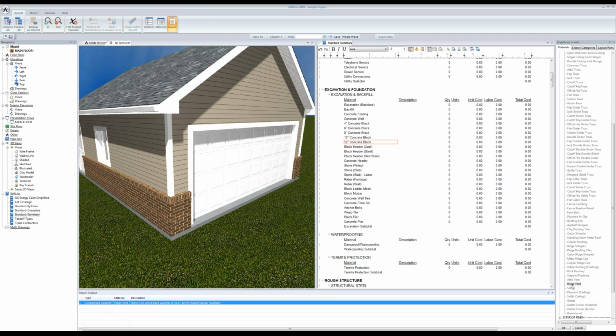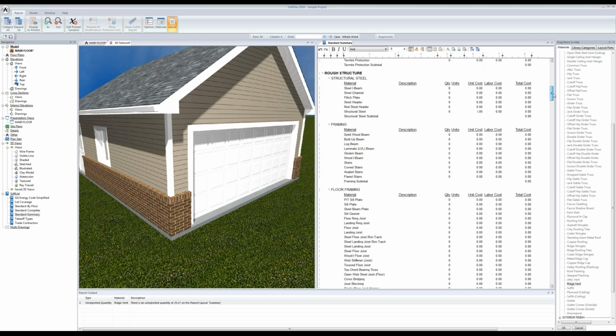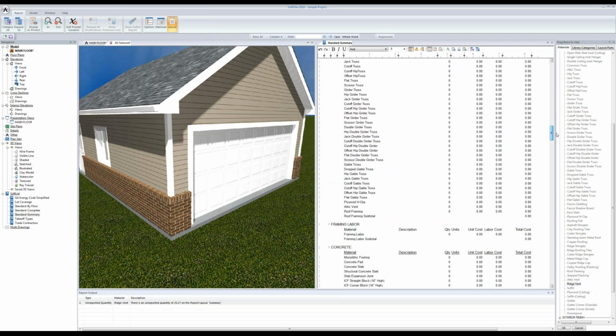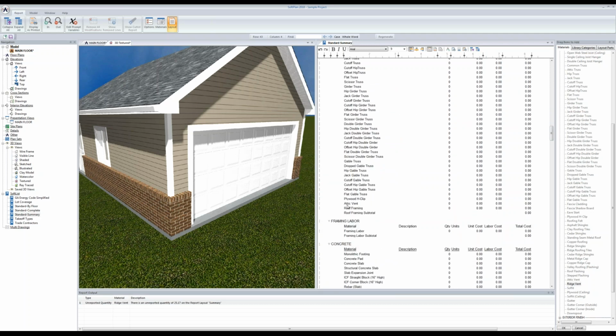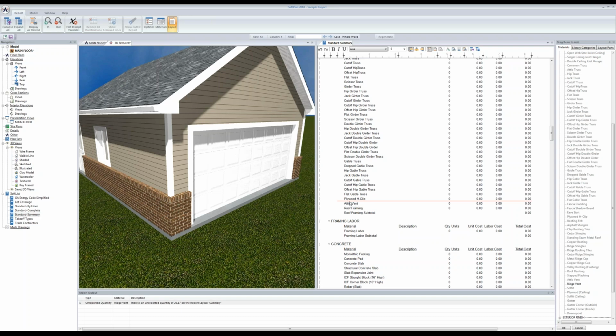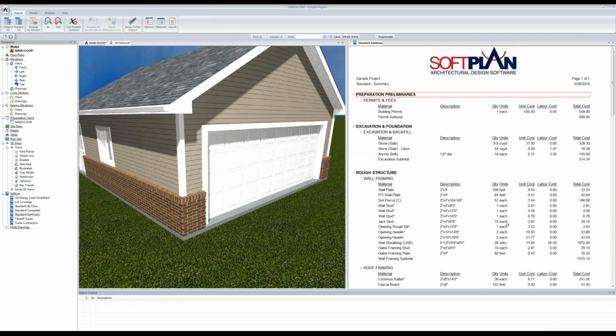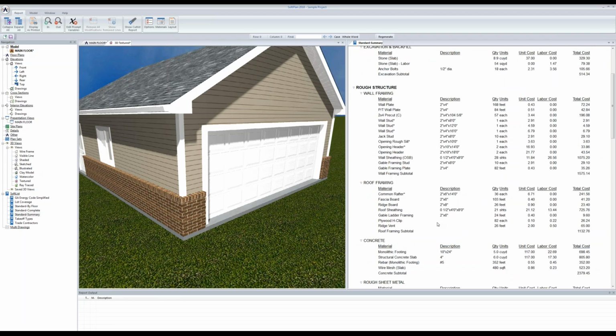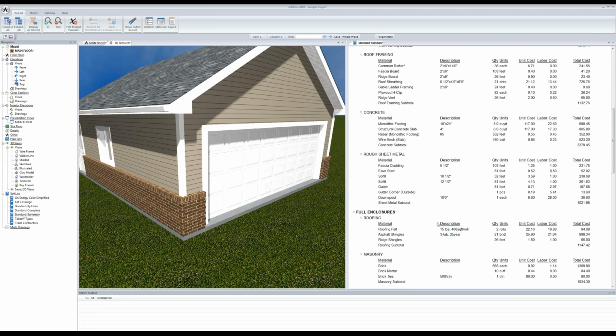So to include it in the layout, locate in the report the spot you want to include it into. In this case, I'm going to locate the original attic vent. Although I've excluded it, so it will never count, if it were to be enabled again, it would go into this location. And I want the ridge vent to fall into the same location. I can do so by dragging and dropping its name into that part of the layout. I'll hit OK. Now that I have ridge vents included in the layout, no longer do I get the error in the output at the bottom. And if I scroll down a little bit, we'll eventually come to, oh, there it is, the ridge vents that I've estimated.